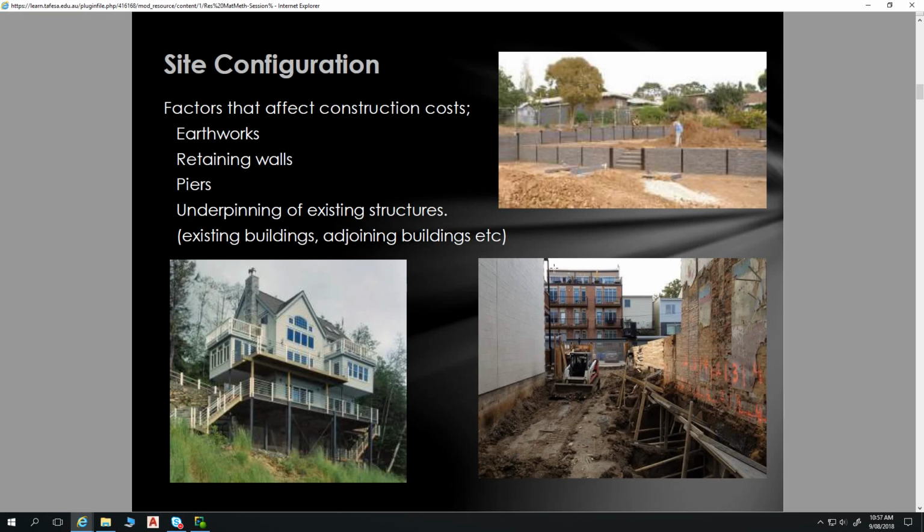That is basically a report produced by somebody who's gone along, and let's say this is our adjoining building here. They will do a thorough assessment of that building, including the footpath and anything around the site that would give indication of pre-existing conditions. They will look for, okay, we've got this control joint here in this brickwork. It's 10 millimetres at the bottom, 14 millimetres at the top. That's indicating some sort of movement of that slab, or stresses on that slab.